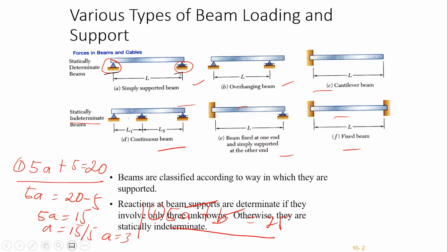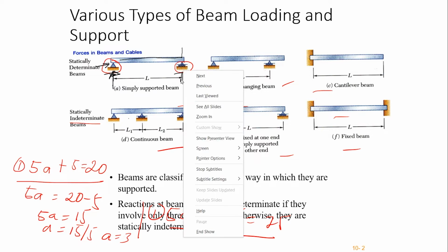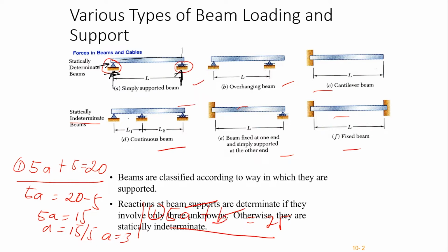Support, no? So if you know the support, you will know the reaction. But if you don't have any idea of what's going on with the support, you will be lost. So for example, here is a support, like a triangle. So we know that it has a vertical and horizontal constraint just to be fixed. And here we have a support because this member has a weight. So eto, yung bigat ng beam susuportahan dito ng roller. Pero at the horizontal, left and right, we don't have any support.